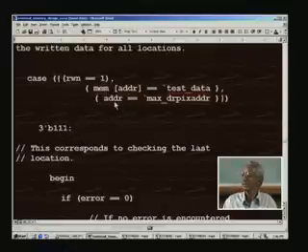And the third case is when the address is the last address. For example, the address is the current address which is running in the design, and it will be incremented right from 0, then 1, 2, 3 and so on, it will go right up to 65535, and when it touches that value, that is what is here, this equality will be satisfied, then a logical 1 will be returned, and that is this here.